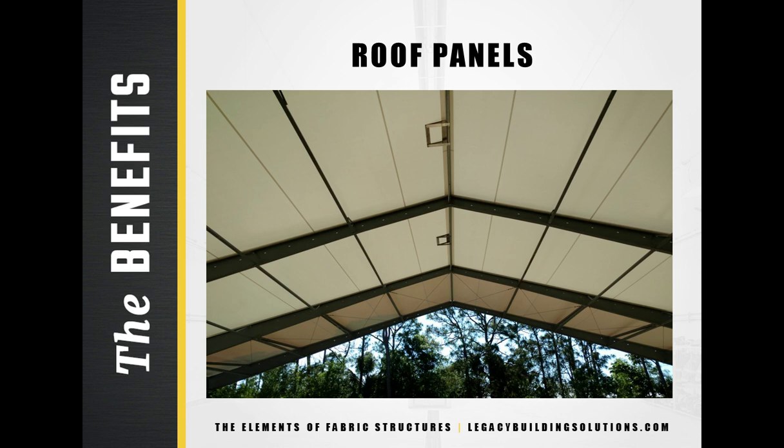Each roof panel is welded together to create a waterproof sealed exterior membrane. This system also uses horizontal mechanical tension to stretch the fabric to the recommended level, keeping it taut and preventing any friction for the life of the building. This system provides regular support and tension for fabric both vertically and horizontally, which is critical to ensure a wrinkle-free finish and a long fabric life.